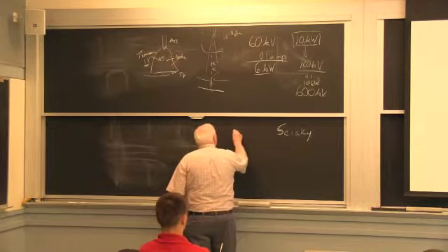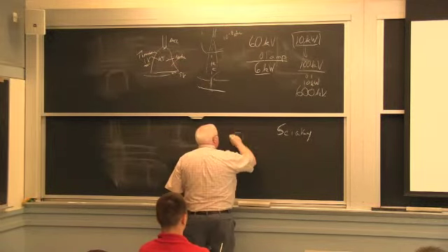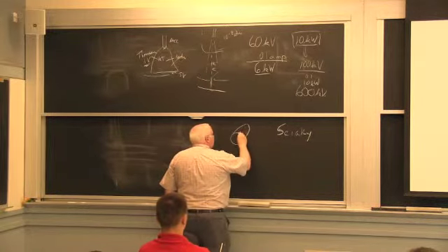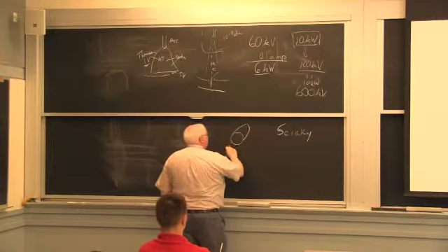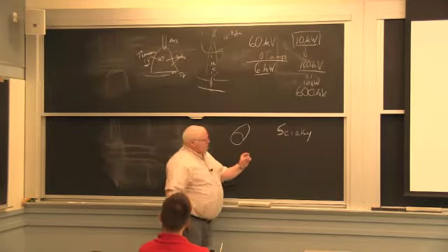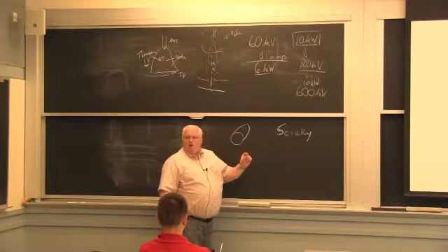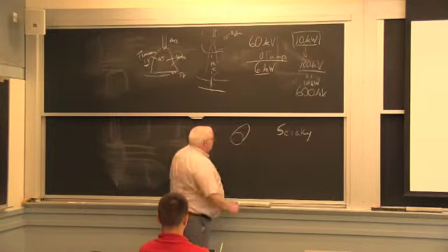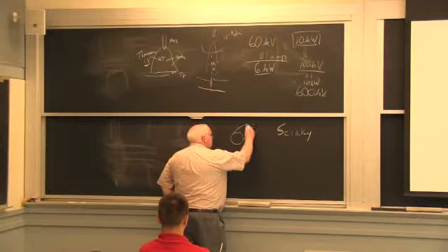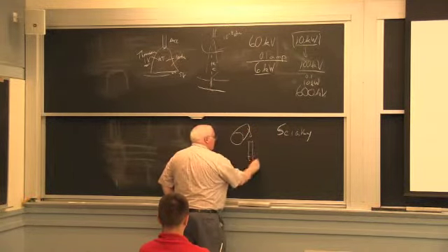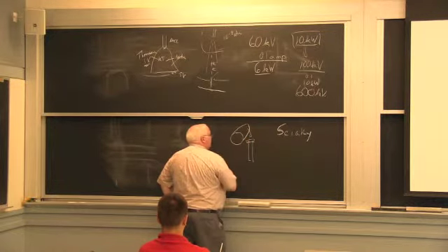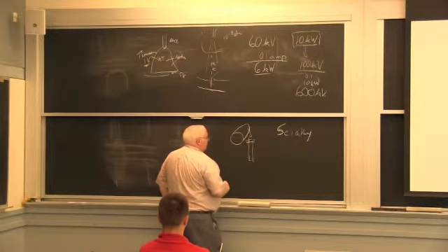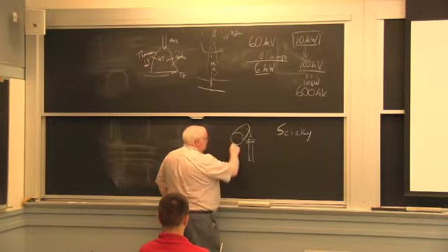So I've got a cylindrical shaft. I'm looking down the shaft, and it will have lobes on it like this. I'm not going to try to ever draw that in 3 dimensions, but the lobe may only be half an inch wide or 3/4 of an inch wide, just this protuberance, and it comes along as it's rotating around. It hits the top of the valve, which usually has a cap on it, and it pushes it down against the spring, and that's how the engine gets the valves opening and closing at the right time.